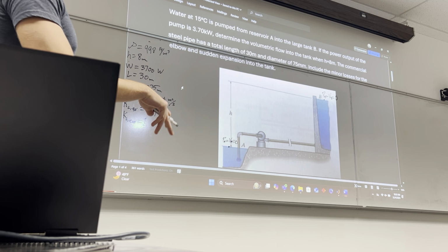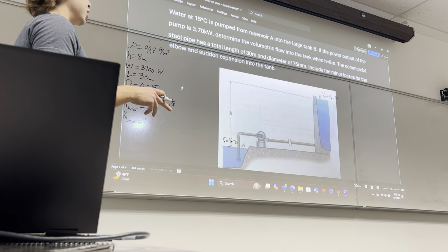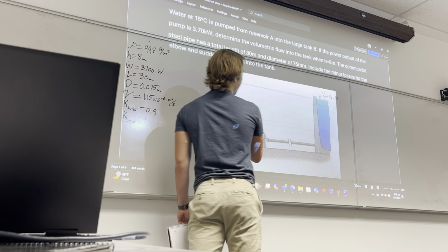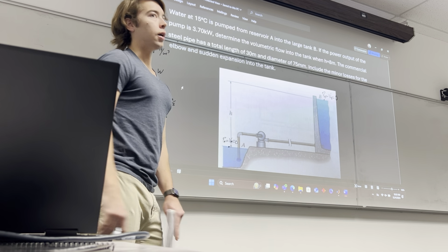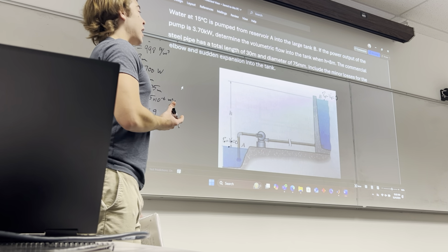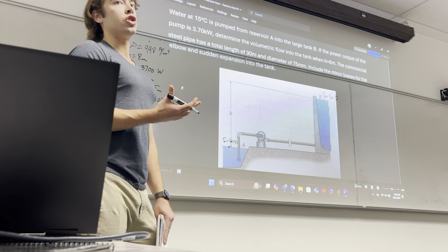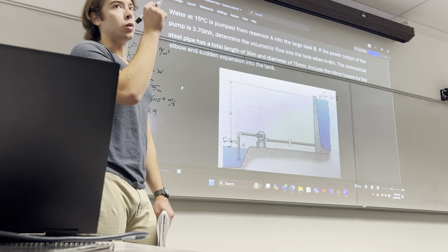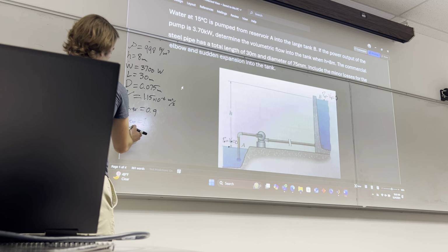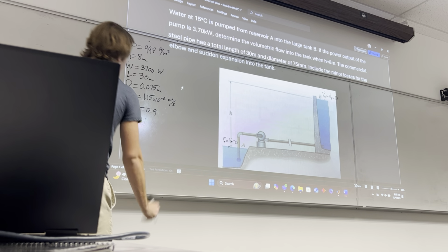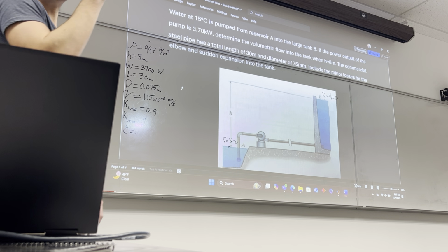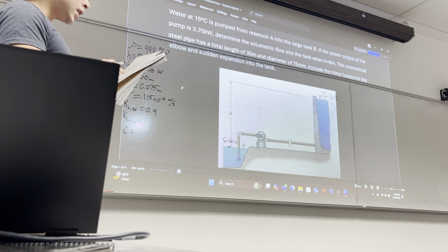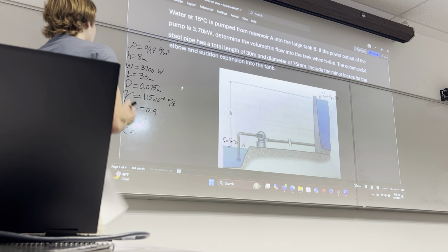Oh, another part of this is we need to know the epsilon value for the surface roughness of this pipe. Again, they don't give it to you, but think about it physically: you can't make a perfectly smooth pipe. There's going to be friction inside the pipe. That's why we're doing this whole thing. Inside of the pipe you're going to have little bumps and imperfections, and you denote that as epsilon. It's basically the height of the tiny grooves in the pipe as it's being manufactured. And they have that as 0.045.